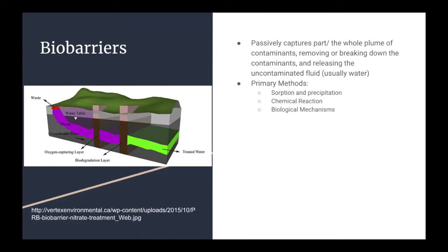Another way to apply biostimulants or bacterial cultures are the biobarriers, which minimize the movement of contaminants. These are installed by digging a large trench. They are usually no more than 50 feet long and 20 to 50 feet deep. Heavy machinery is required for the digging, like an excavator or a bulldozer. Once installed, these require minimal maintenance. Bacteria are often used that outcompete endogenous cultures.